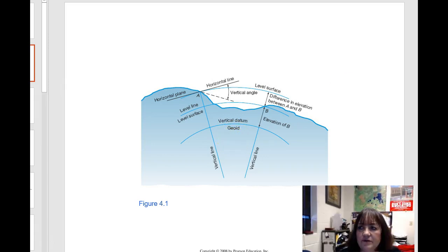And when we refer to the idea of geoid, we're really talking about the idea that the surface of the Earth does not actually correspond exactly to a geometrical or mathematically determined shape. So a geoid is the hypothetical shape of the Earth that coincides with mean sea level and its imaginary extension over land.